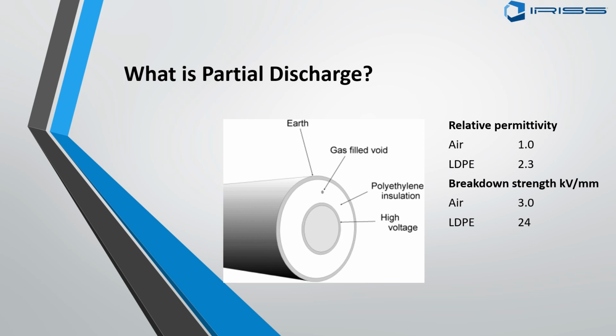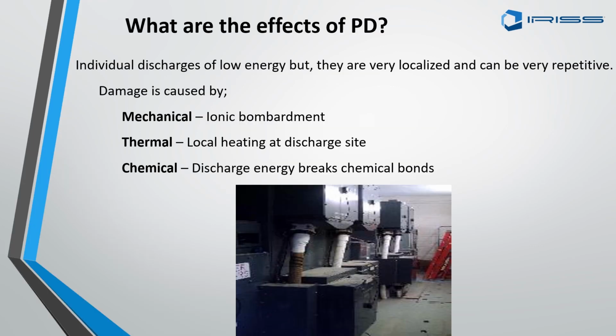And these tend to happen on the rising voltage waveform as you cross zero, and on the falling waveform after you've crossed zero. So, this is what's happening: we have these little voids, and then we have a little sparking and a little arcing going on inside the insulating material. And that has some long-term implications for that material's mechanical strength. What's happening inside there are three things. You have ionic bombardment that's taking place as a result of the electrons that are being released across the gap. We have a localized heating effect. And then thirdly, we have some chemical reactions that can be taking place.